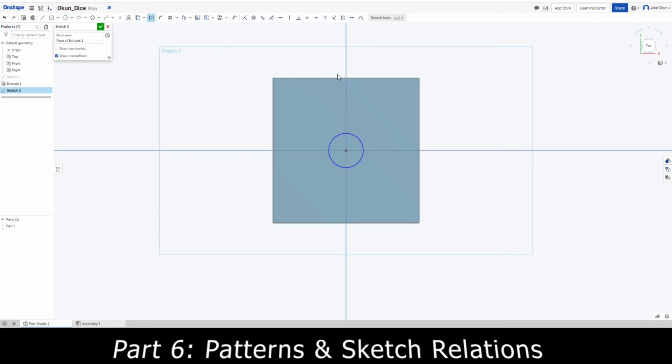So remember, when we're making construction lines, we want to go right from the center. So we'll go to where that point is, then we'll go down right to there. And then we'll be able to make our construction lines. That's very simple. To make the construction lines, we're going to press the line tool and the construction line button. Make sure you have both of those pressed because otherwise they won't work.